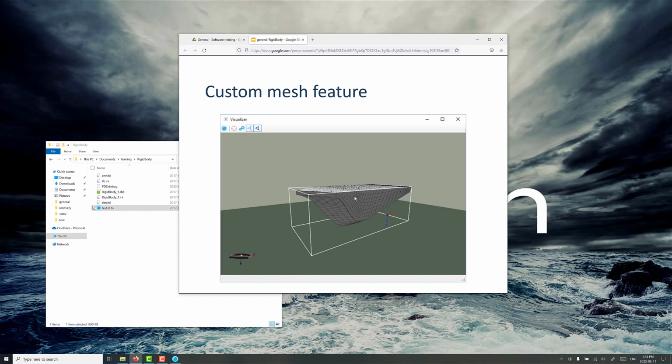Custom meshes, you can create your own mesh as long as it's an OBJ file format and import it into the software. Usually this can take a fair amount of time to set up, but it's a good way to get information from a CAD model. You'll have to do some conditioning in another tool like perhaps Rhino 3D to get it to look nice, and you want to have a nice distribution of elements that are roughly the same size and aspect ratio, and there's some guidance on this in the manual on setting up a custom mesh.